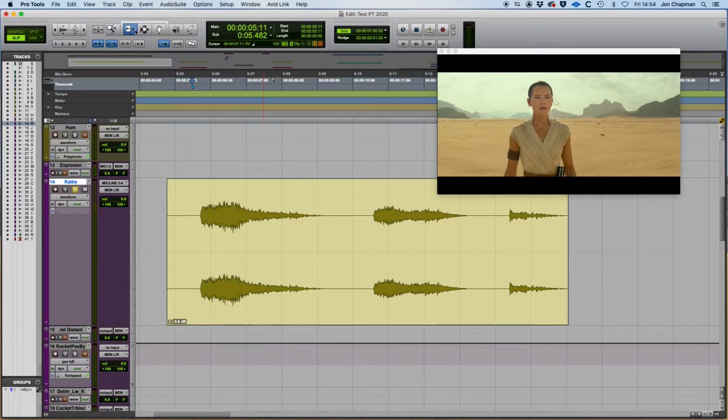So just to explain what these are, you have got the trimmer tool, you have got the selector tool, and you've got the grabber tool. And you can select these individually, like I say, but you would have to keep changing each time you wanted to do a different operation. So the best thing to do is click just in the area slightly above these 3 tools. There's like a little surround area to them. And if you click on that, it lights up blue, and then your Smart tool is in use.